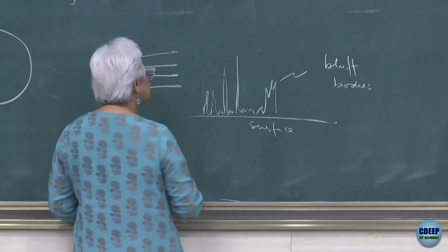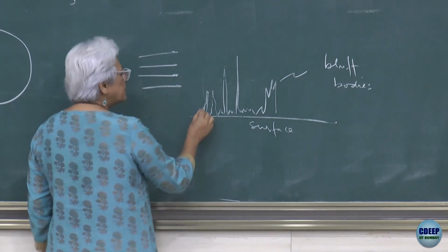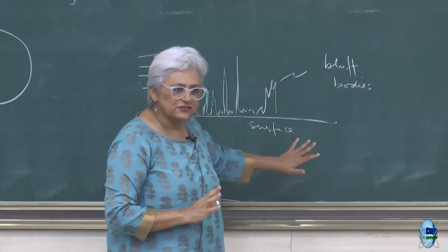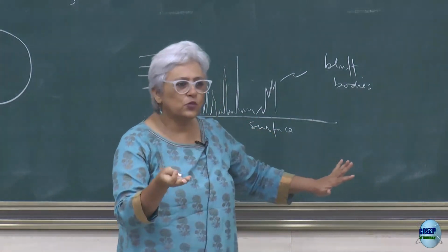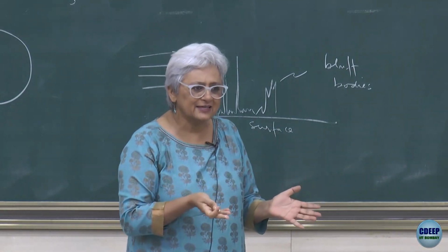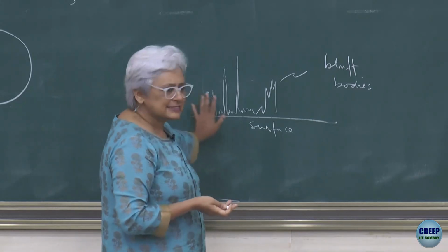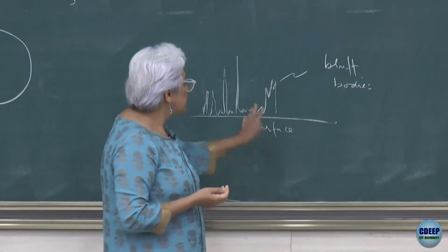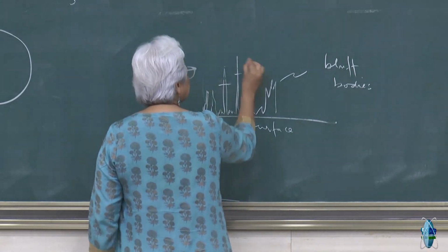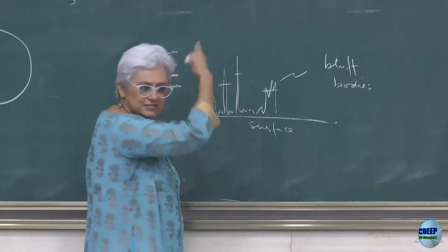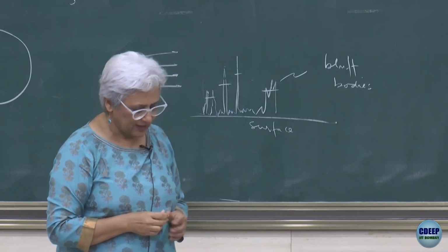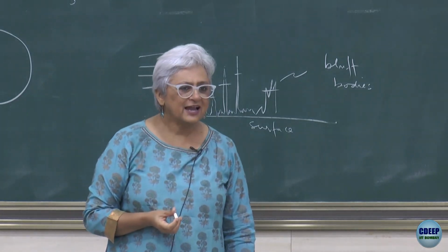Now, why am I showing it at the tip is that all of us know that by the time we are moving close to the surface, the wall law starts kicking in, and so your fluid velocities are going to slow down drastically. So, where is the collection happening? The collection is really happening at the free tips of these roughness elements. So, that is sort of the way of thinking about it, right.